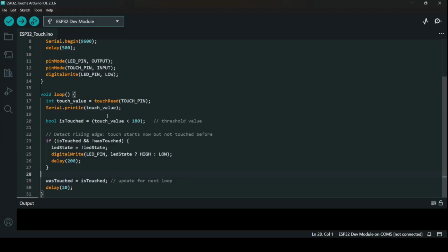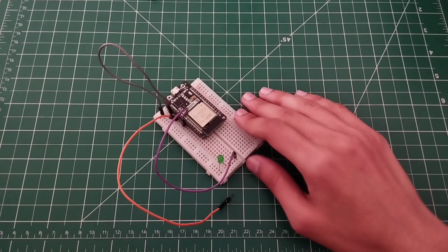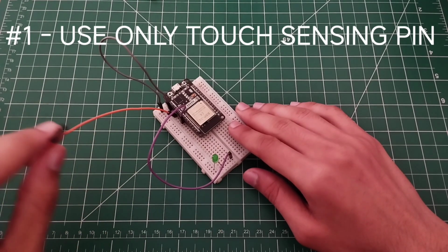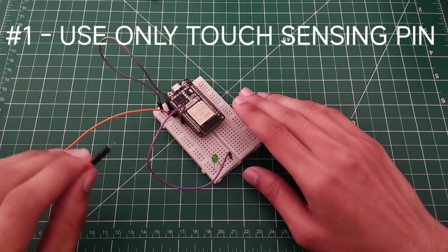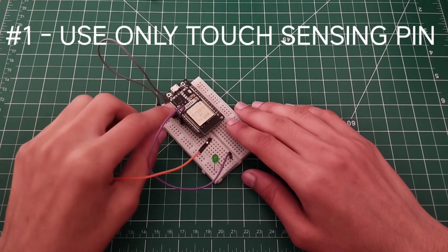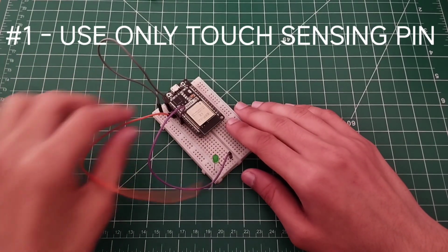Now let us move on to some of the common mistakes that you may commit in this project. The wire that you are going to touch should not be connected to any pins other than touch sensing supported pins, right? So currently this pin is connected to D4, which is touch sensing supported.